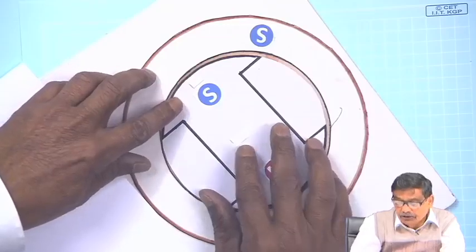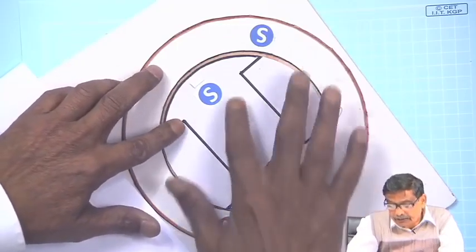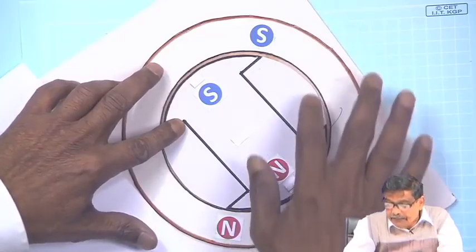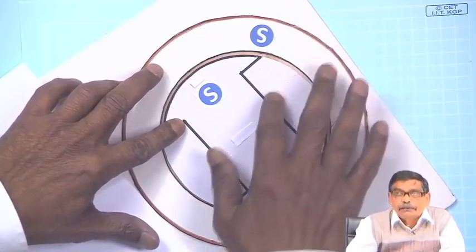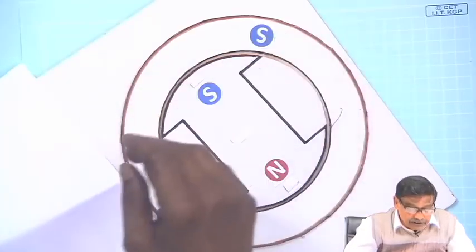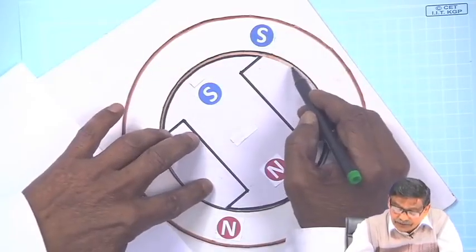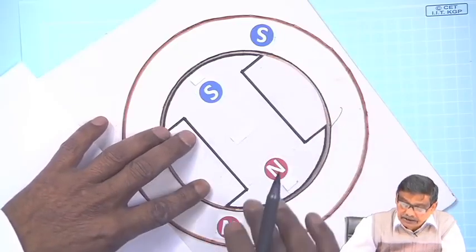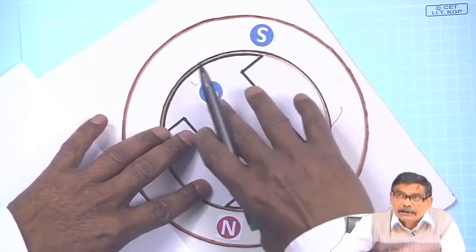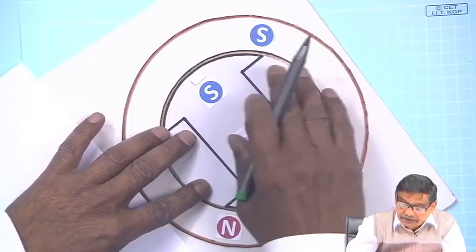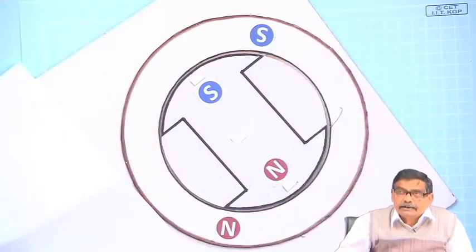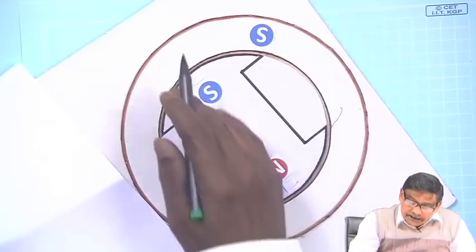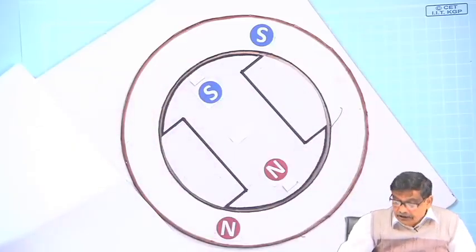You also notice this part can rotate, this part is stator. There must be some air gap in between, that is this portion. A uniform air gap will exist in any rotating machine, so that the rotor can freely move and should not strike the stator iron parts. For smooth rotation there must be some air gap, you cannot avoid that.